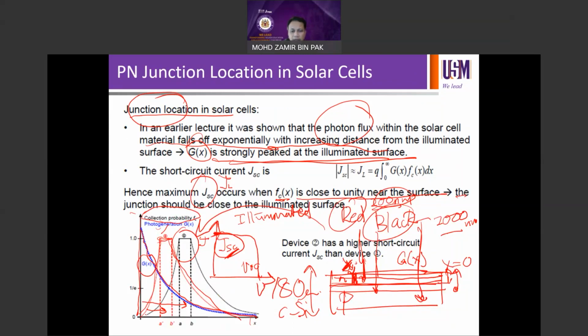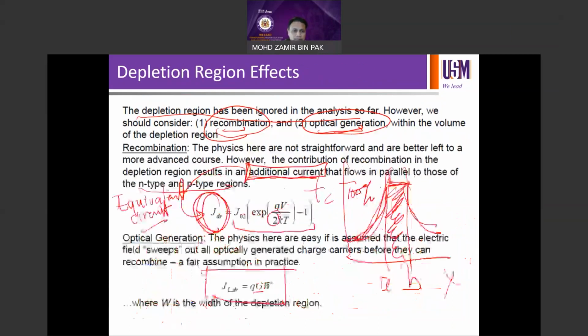We have seen that if you compare 200 nanometer of depth with 2 micron, or 2000 nanometer, you should expect the 200 nanometer device to give you better short circuit current density. But this is not necessarily true for thinner junction depths, because more factors come into play that you will learn eventually in the device part on solar cells.